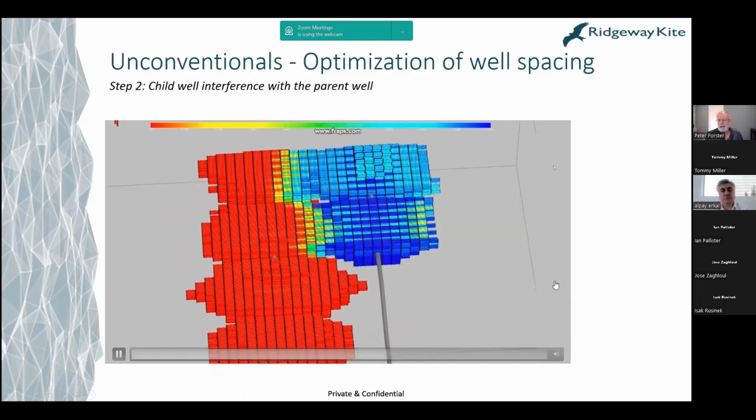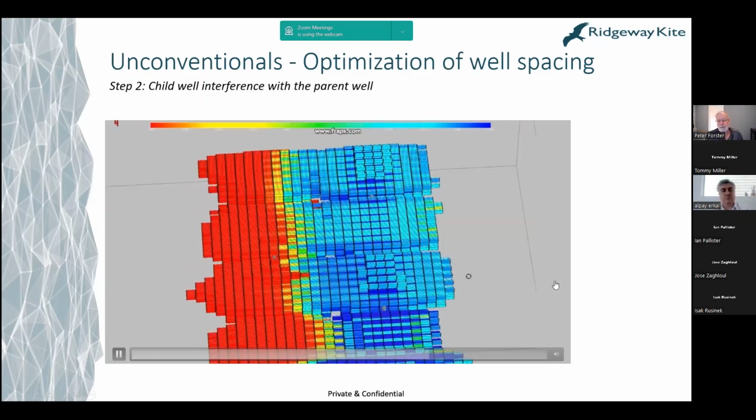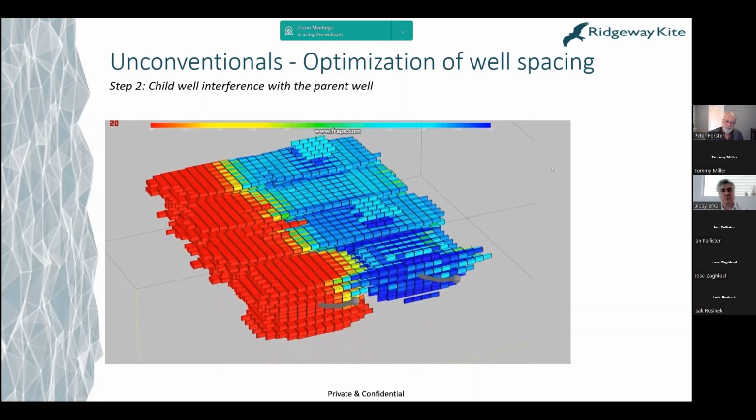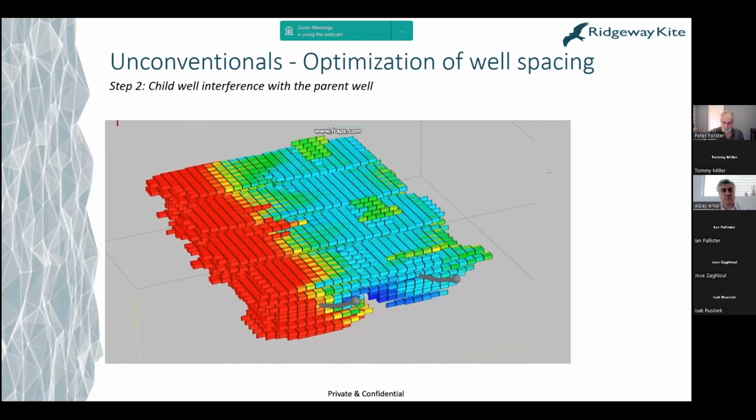So we're dynamically capturing the interactions between the wells, and we are not forcing the fractures to go in any particular direction. We're just changing the underlying characteristics of the geomodel to capture the effects that we want. So we're calibrating the underlying aspects of the model to get the dynamic behavior that matches our history, so that we can then use that dynamic behavior as a predictive tool.